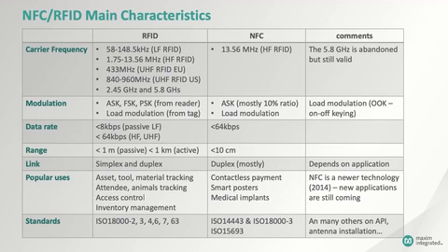Many RFID techniques will work at around a meter for passive tags and as much as a kilometer for active tags. That difference illustrates some significant differences in use cases between NFC and more generic RFID. With its short range, NFC can be more secure than generic RFID, simply because it's more difficult for an attacker to eavesdrop on the communications. And that security makes NFC much more suitable for payments and access control than generic RFID.